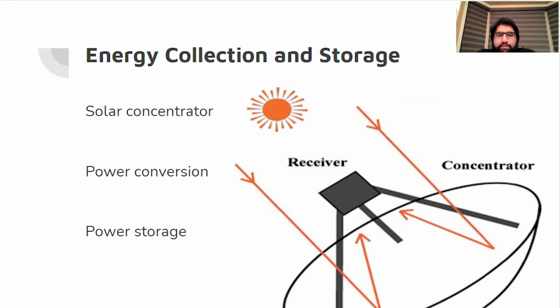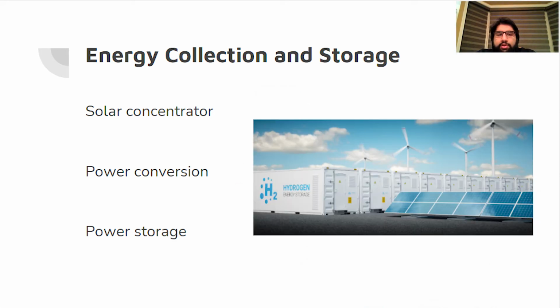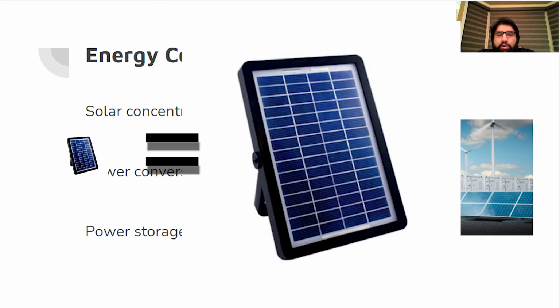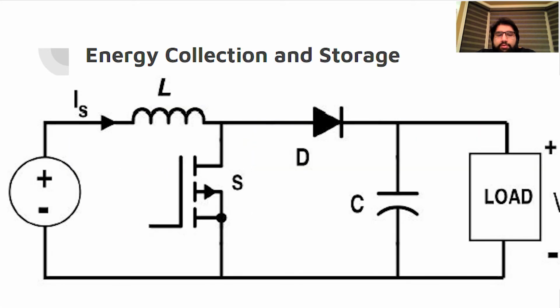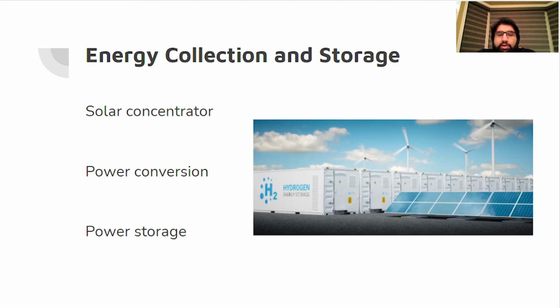The device will receive its energy from the sun. A concentrated photovoltaic will be the most weight-effective way to do this. By concentrating the sun with lightweight reflective mylar onto a small, efficient solar cell, the same power can be generated from a smaller solar panel as one much larger and heavier. The power generated from the concentrator will need to be converted to a useful voltage before powering onboard systems or being stored in the battery. Calculations involved include solar heating of the system, energy conversion efficiency and maximum energy use, and storage and output.